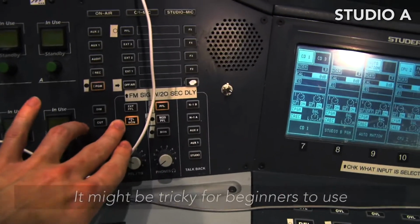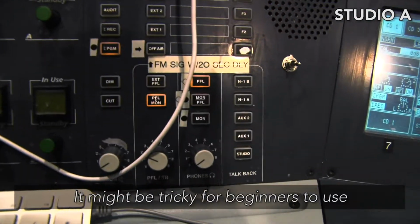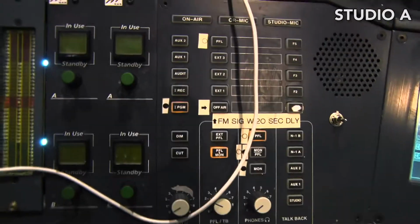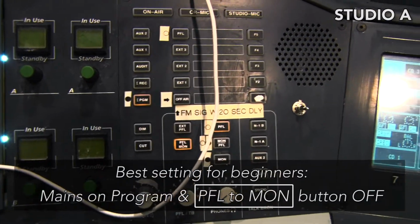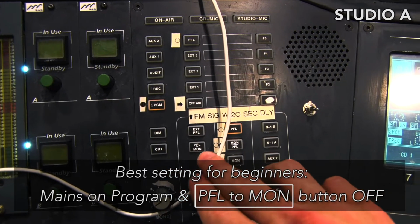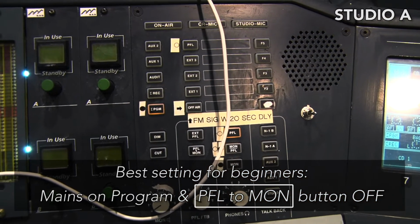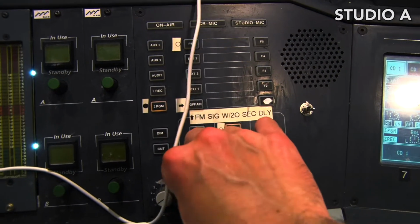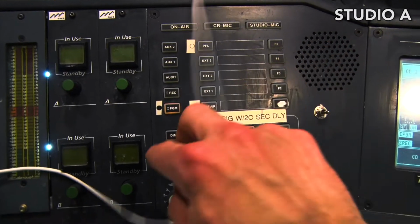I really love this feature, but I don't necessarily recommend it for beginners because it's another thing that can just trip you up. The best setting for beginners is how you see it right now, with your mains on program and your PFL to monitor button off. This will just make sure PFL comes through your onboard speaker and your program will come through the mains.